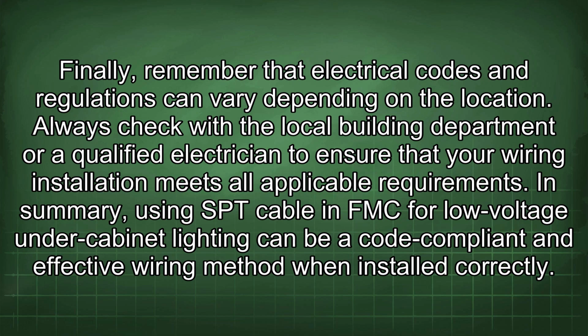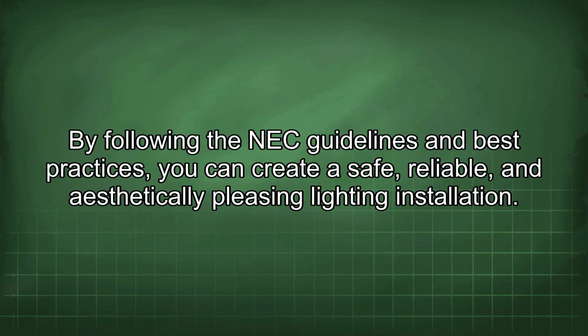requirements. In summary, using SPT cable and FMC for low-voltage under-cabinet lighting can be a code-compliant and effective wiring method when installed correctly. By following the NEC guidelines and best practices, you can create a safe, reliable, and aesthetically pleasing lighting installation.